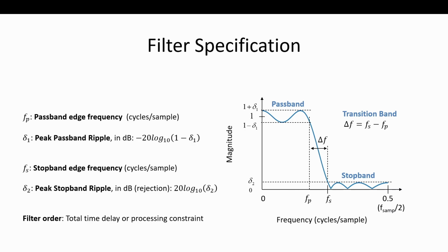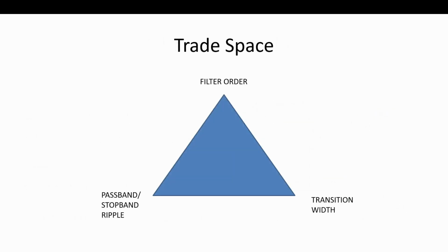But arbitrary FIR filters can have arbitrary phase responses, and phase is often a very important parameter in the design. So if it's not linear phase, then you have to pay attention to phase. We're so used to seeing magnitude responses and not thinking about phase, but just know in the back of your head that it is a very important design parameter that we can ignore here because I said it's linear phase. The phase is just a straight linear slope over frequency.